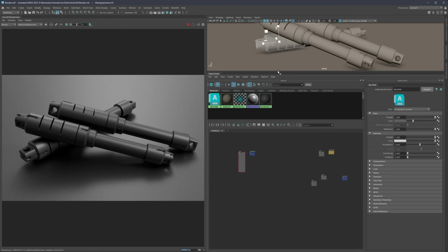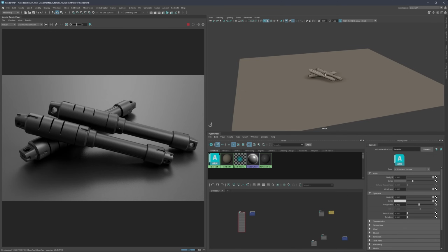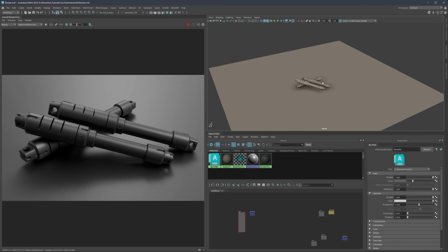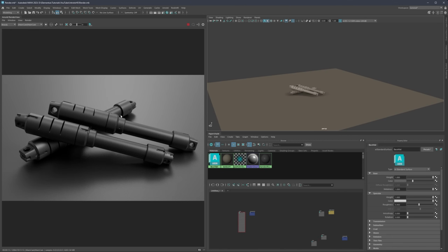All right, so now when we have that established, let's go one step further. One step further is going to be establishing the light. So I would say that for us, the lighting is going to be much more important than the material, because what we need to establish here is proper contrast so that we can clearly see what we're trying to present. And so the material is going to be kind of like a secondary option. We can advance more and more into material, but we don't have to if we really don't want to. So right now I just want to add, let's say, one light that is going to bring a bit more contrast to the scene and just break down all this, let's say, gray area.